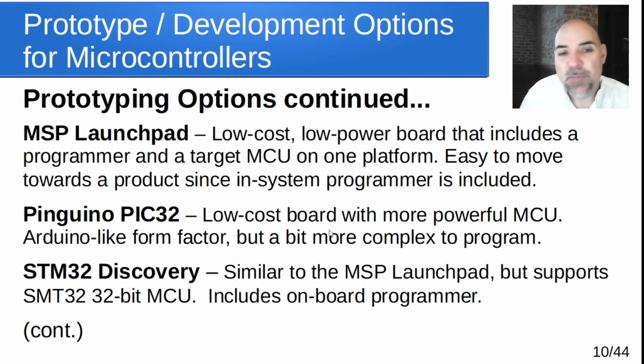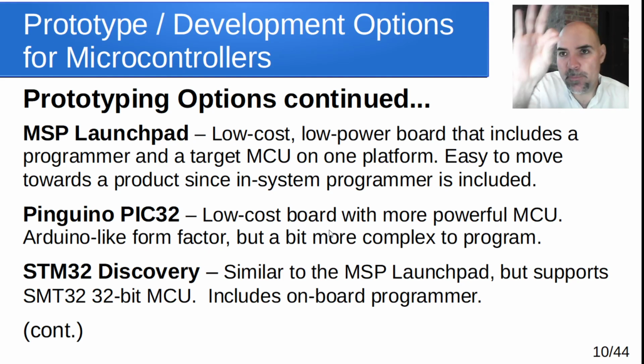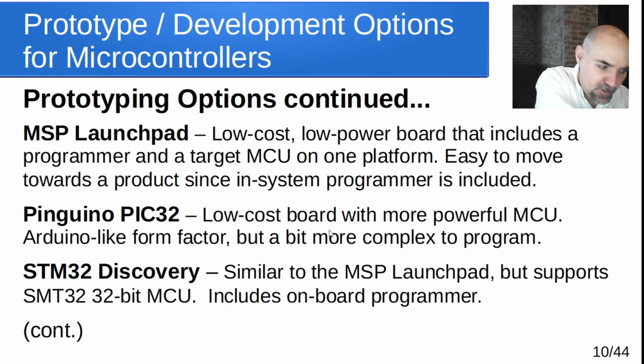There's this thing called MSP LaunchPad boards. The MSP LaunchPad is a Texas Instruments specific form factor, but those are low power boards. They have a programmer and a target microcontroller on one board. So there's a little part of the board that acts like the programmer that programs the other part. The cool thing about that is if you did want to move towards a mid-volume or higher volume part, you could use the programmer on that board to program an in-system microcontroller as well. So it's easy to move towards a full build version using that in-system programming capability that the programmer portion of the board allows. In other words, rather than having it program the chip that's on the board, you can have it program a chip that's in your design somewhere else.